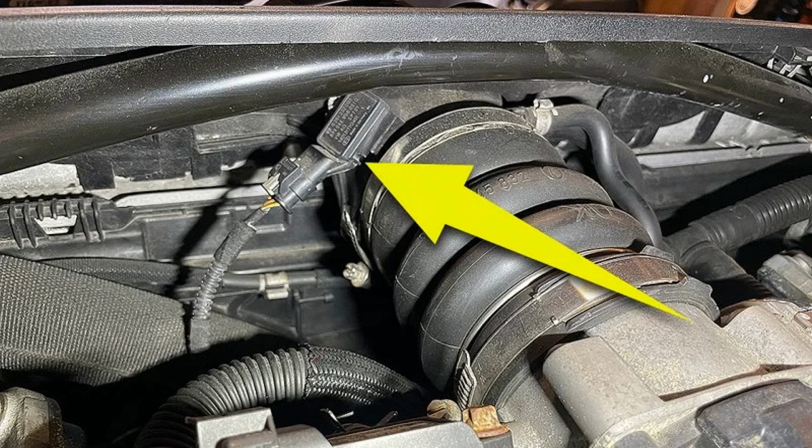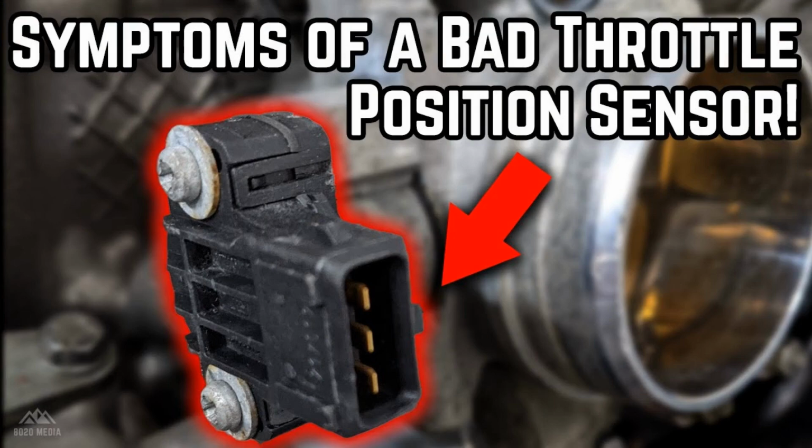What are the possible causes of code P0068? The PCM may set a P0068 code for a variety of reasons. These include a defective or faulty MAP sensor, a defective or faulty MAF sensor, a defective or faulty TPS, a vacuum leak, corroded or damaged wiring for the MAP, MAF, and/or TPS sensors, a dirty or defective throttle body, and PCM problems. A defective or faulty MAP sensor can cause code P0068.